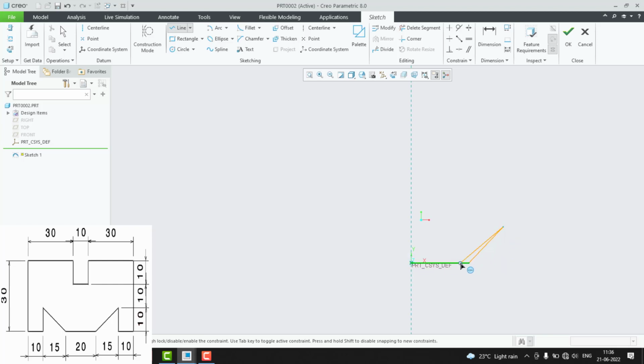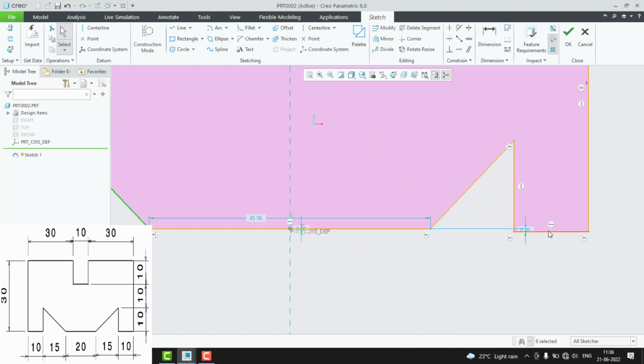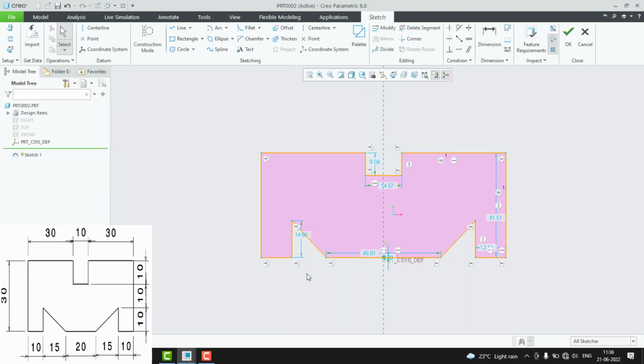Same thing, we'll try this sketch, quite an easy one. Okay, I'm going to draw the rough sketch. Sometimes you won't access the references, so you can simply leave it now. You can proceed further to complete the rough sketch like this. And I just need to mirror everything. Just select the mirror and replicate the same. Dimensioning, it is not exactly coincident. Just select both and make it coincident. Same as in SolidWorks.